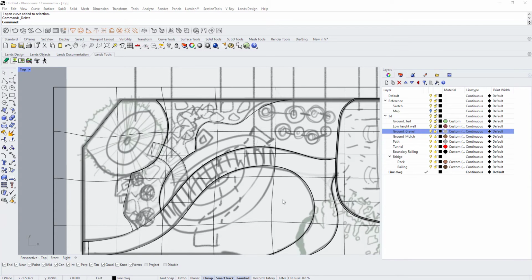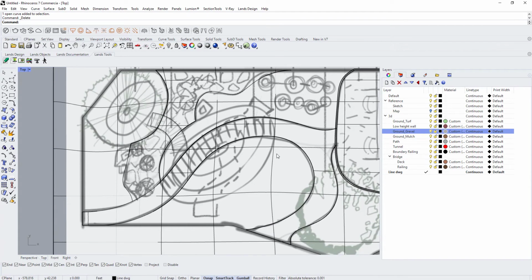Now, a common problem in our class is how do we make underground tunnels. In this case, I'll try to make a simple tunnel with the pipe command, but you can also try the sweep command if you have a different cross section for your pipe. All I have to do is create a curve that follows the center line of our pipe very roughly, because the sketch is very rough. If you had a CAD drawing, you could just offset.